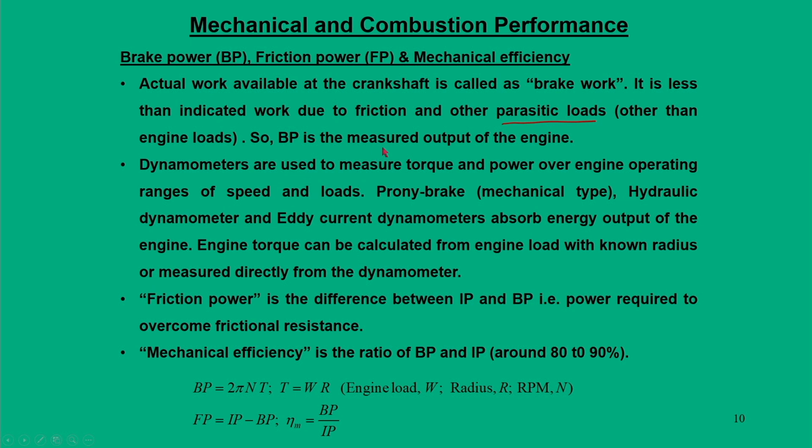So, for brake power we require a dynamometer, and there is no method in which we can directly get the friction power, but friction power is nothing but the difference between the indicated power and brake power. That is the power required to overcome the frictional resistance. Once we know the indicated power and brake power, then we can calculate the mechanical efficiency.